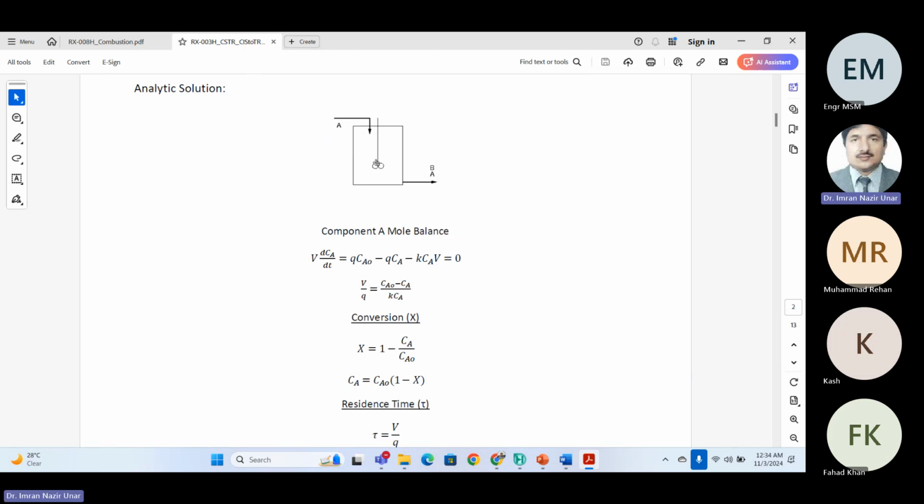Whatever is not balanced going in and out is the rate of increase of that thing in the system. So this is nothing but the rate of moles increasing per unit time within the volume of the reactor, and it says if this is at steady state, then this will be equal to zero. Means this derivative has nothing to do.